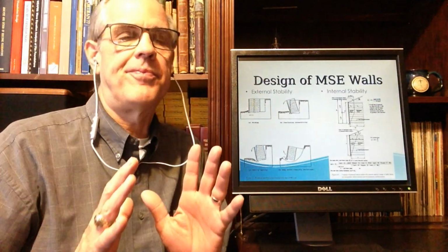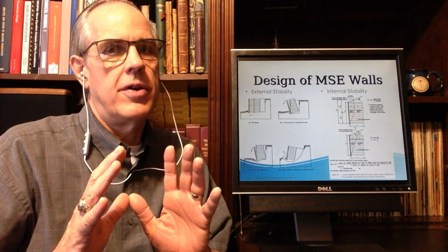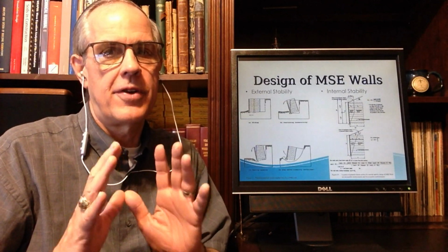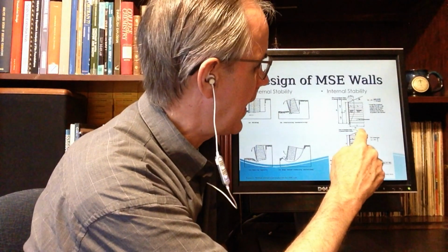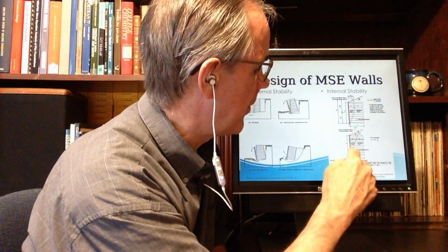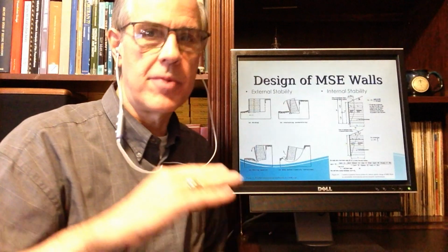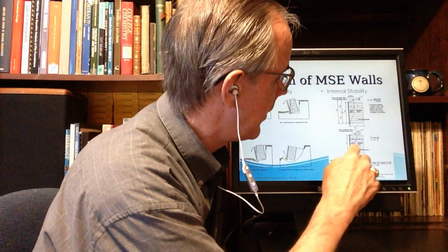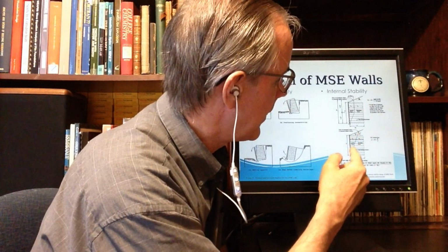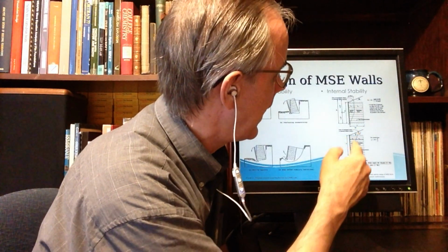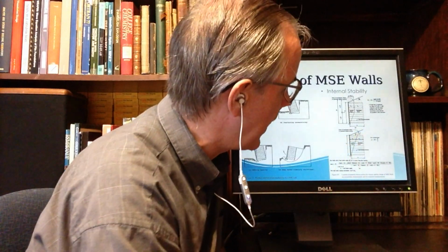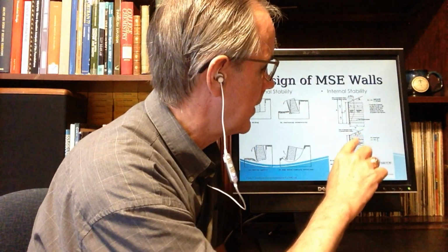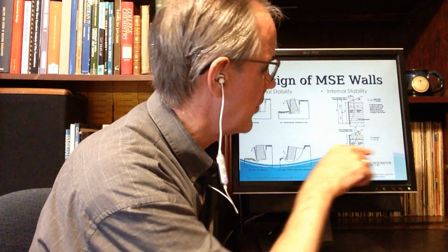In my lectures on basic earth pressure theory, I basically say that what earth pressure is all about is that you've got a mass of soil, a triangle. If we assume a planar failure surface, and let's just do that for the minute, it assumes this, and this surface has an angle of psi from the horizontal right here.